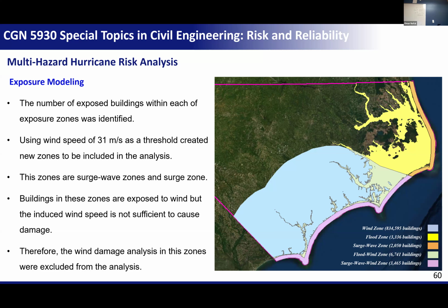So here we are going to find combined damage from storm surge, wave, and wind. Here, just damage from wind. Maybe you will find tiles moving from the roof, but there's no water. Here, there is just the storm surge and wind, so we need to use different functions for each. But when I did the analysis, rather than dividing it into many zones and developing a separate function for each zone, I listed every building and looked at what hazard it's exposed to.